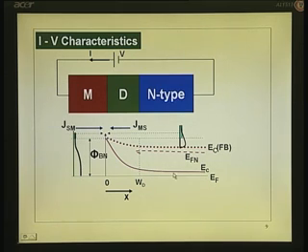When you forward bias, this goes up, the dotted line, and the Fermi level, which you can call the quasi Fermi level EFN, also goes up. For the total carrier concentration here, you can use the thermal equilibrium situation, and that will be practically equal to the dopant concentration. The entire area under this curve gives you the total concentration N 0, which is virtually equal to the ionized dopants.